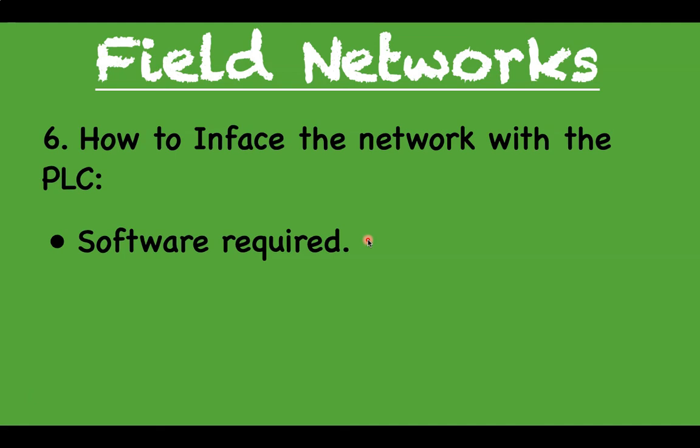You also need to know the hardware required. In some cases, you may need a special PLC card or module in order for the network to communicate with the PLC. If the field network is Ethernet based and uses the same protocol with the PLC, then you can just get an additional Ethernet card from the manufacturer to communicate with the field network if you do not already have a spare port on your PLC.